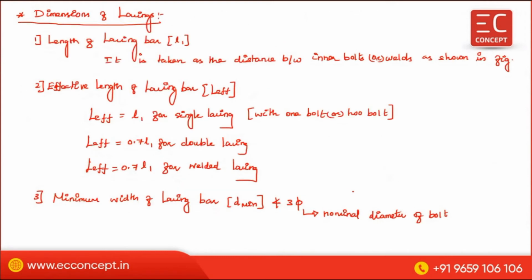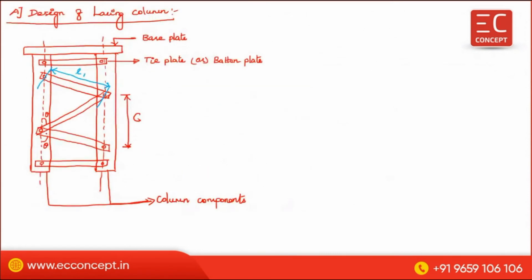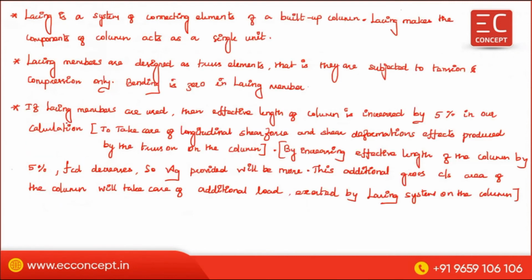What they are saying: in this lacing system, the spacing, the width, the thickness, this angle, everything shall be kept the same or uniform throughout the length of the column, so that the analysis will be simple and the load transfer is also symmetrical. So this is the point.